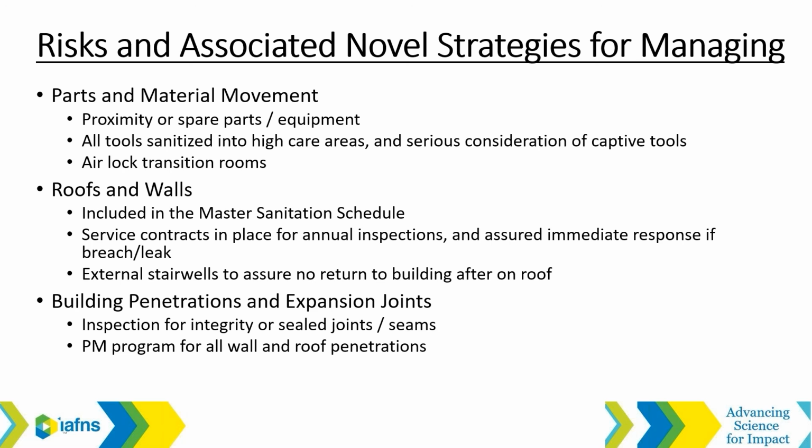And then whether it be from a wet to a dry room, or outside to inside airlock transition room, so that there's not the possibility of two doors open, drafting unfiltered, uncontrolled air across a processing facility.